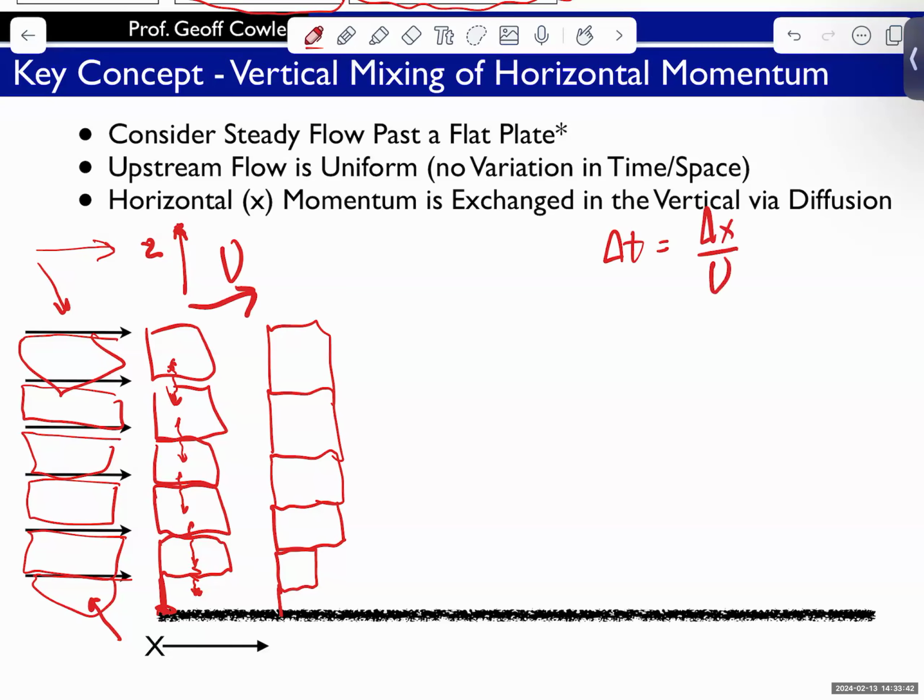So there's still diffusion going on, and now there's an interchange between these two parcels we'll think about. So up here, these parcels, they're exchanging momentum, but because they have the same momentum, their individual momentums don't change. Down here, their momentums are different. So momentum likes to mix things. I'm sorry, diffusion likes to mix things, keep them the same. That's what diffusion likes to do. It's trying to make the momentum between these the same.